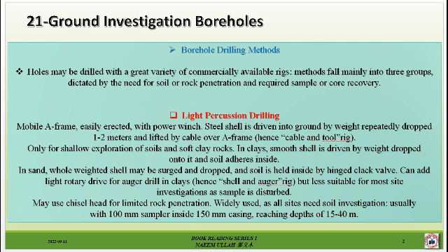Light percussion drilling. Mobile A-frame, easily erected with power winch. A steel shell is driven into the ground by a weight repeatedly dropped 1 to 2 meters and lifted by cable over the A-frame, hence cable and tool rig. Only for shallow exploration of soils and soft clay rocks.